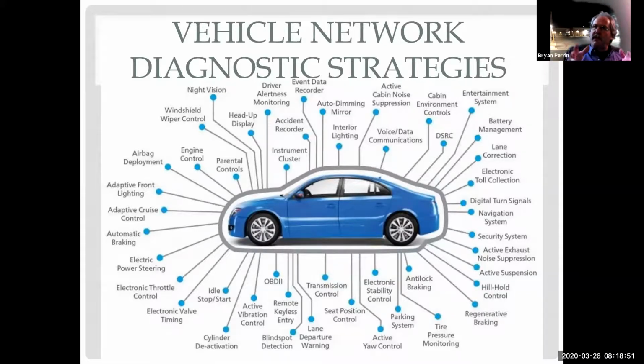I don't want to put all these on one network. Like I talked about yesterday, we're going to want to use different networks because not all these modules need to work at the same speed. So I don't need to invest the same amount of money into every network, and some of these modules are probably more important than others. For example, I'm guessing that my automatic braking might be more important than my tire pressure monitor. It might need to get information and send information out at a much faster speed. Is that a fair guess? Yeah, right.